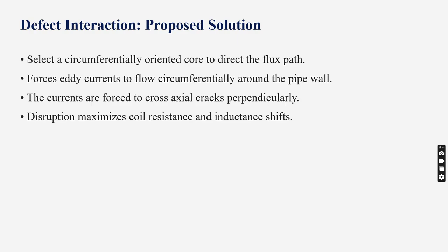Because the currents are focused to flow in this direction, they hit an axial crack perpendicularly. The crack acts as a high resistance obstacle, forcing the currents to flow under or around it, which causes a significant change in the coil inductance and resistance.